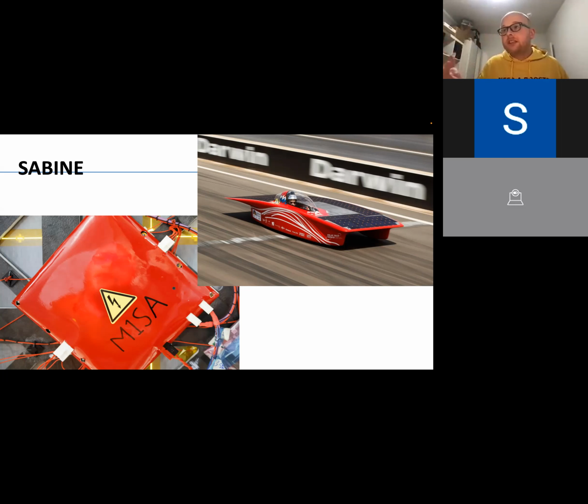And then what you will see once you start monitoring that is that all those voltages are a little bit different, because they're all placed in series and they all get a little bit different irradiance. And once you start noticing those differences, you can see which cells are weak and which cells are strong.